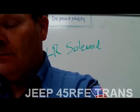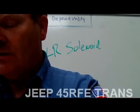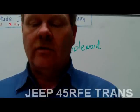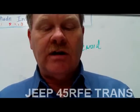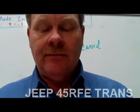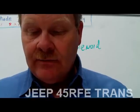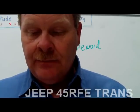Maybe A. How would I do a shift lever position test? That's a good thing to do. When the 45 RFE transmission is in third gear, which 2 clutches are applied? Underdrive and overdrive. So we already looked at that.